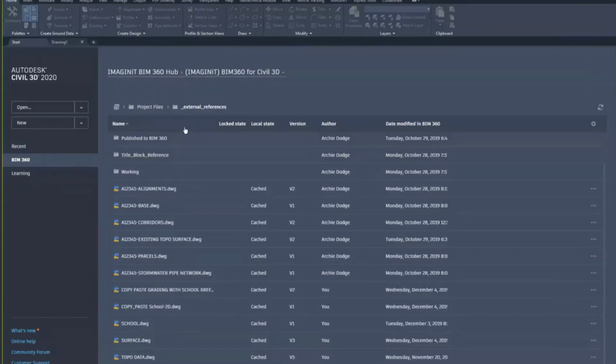And this carries over into the files themselves. When you click on XREF or you type in the XREF command and attach a DWG for an XREF or any other file for an XREF, you would be able to map to that BIM 360 drive location to get to those files. If you're using data shortcuts, your data shortcut working folders and file paths can all be set to those BIM 360 locations as well. So the desktop connector and the update there is really just enabling the fact that you can access your cloud-based locations as opposed to limiting to your local drives and network drives as we had in the past.